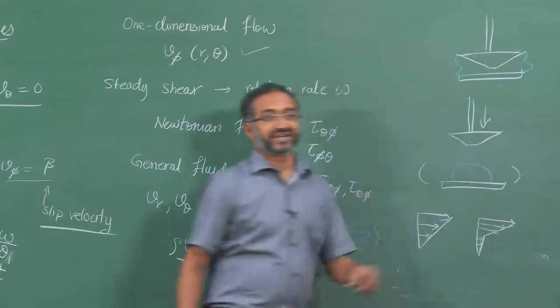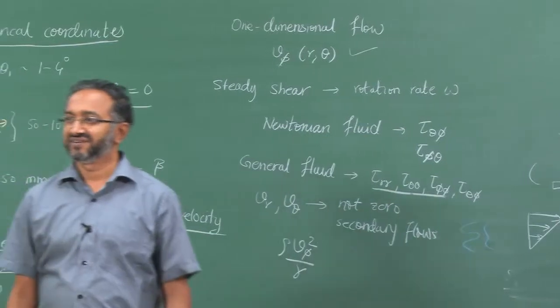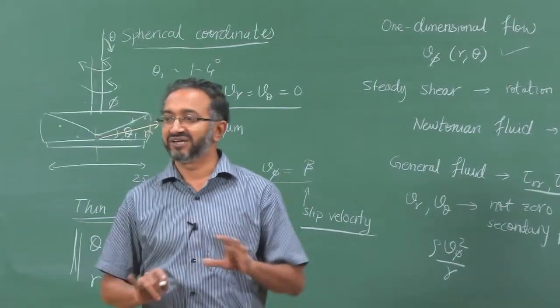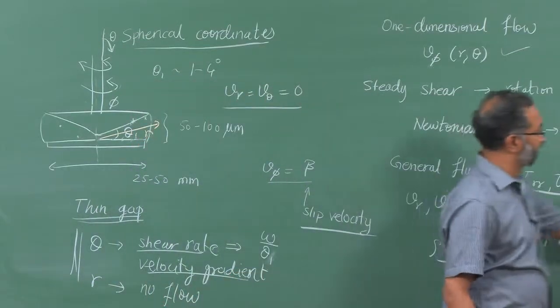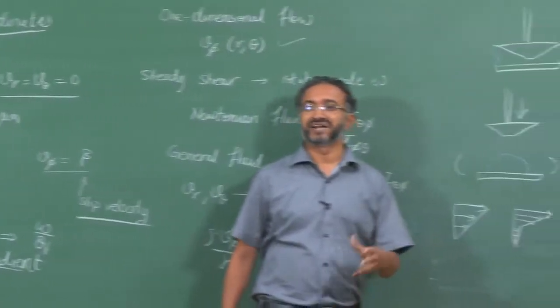So the material breaks into two different shear rates. Part of the fluid, even though you are imposing from outside only one rate omega, and therefore you assume that the strain rate in the material is this, but the material undergoes what is called shear banding.